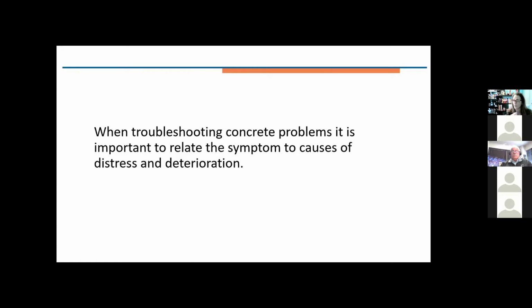But it has everything from a piece of wood in it to some drying shrinkage cracking to some staining due to iron ore in the aggregate. It has all of these issues, but to me, those are all blemishes because the product itself is gorgeous and it is serving itself well, and the drying shrinkage cracks are maintained in the proper location.